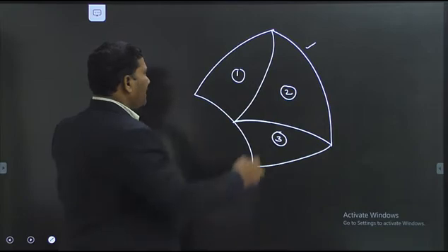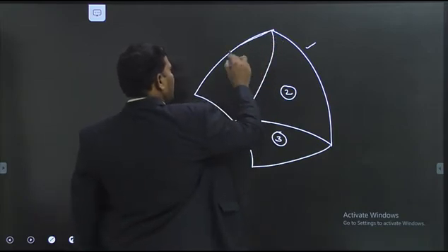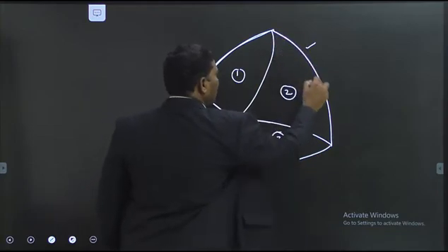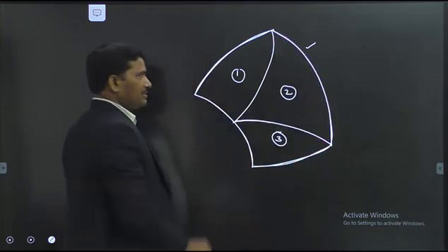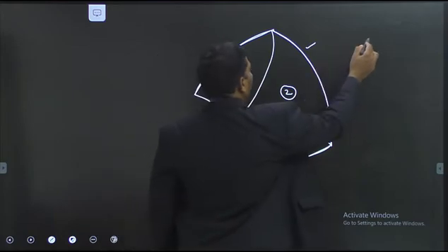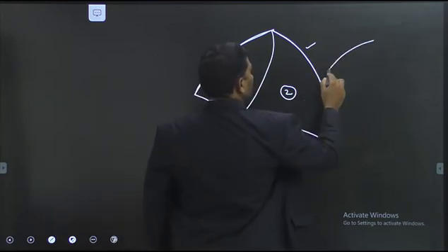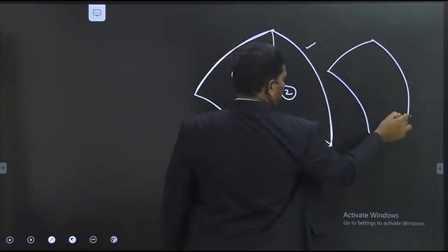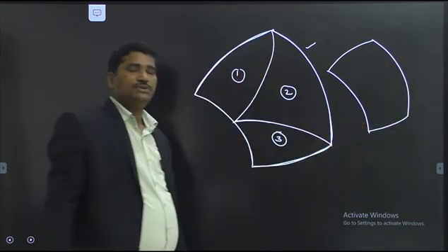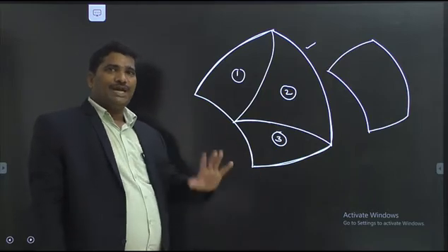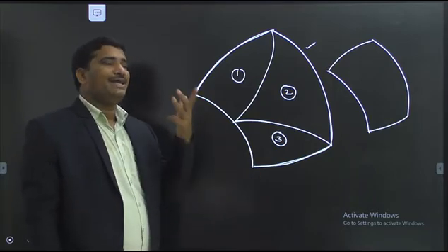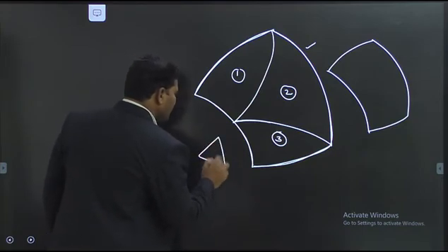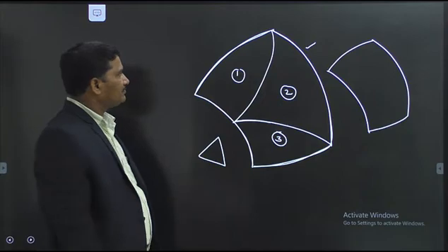So can you discretize this domain using a triangle with straight sides? No, not possible. Let us try. Again, I take the same domain with different sides. We have linear two-dimensional elements. The basic form is the triangle. A triangle consists of straight sides like this with three nodes.